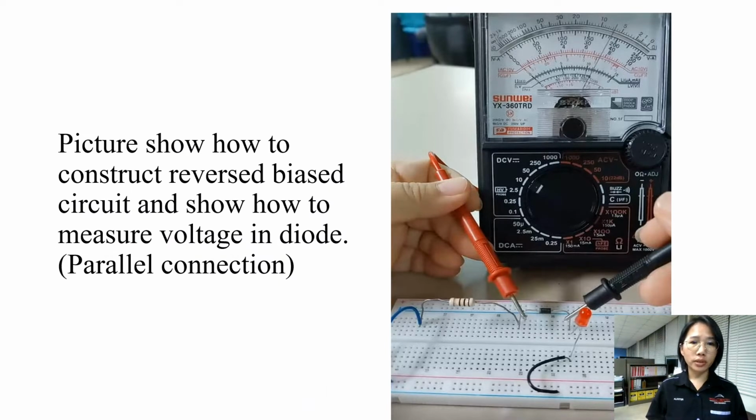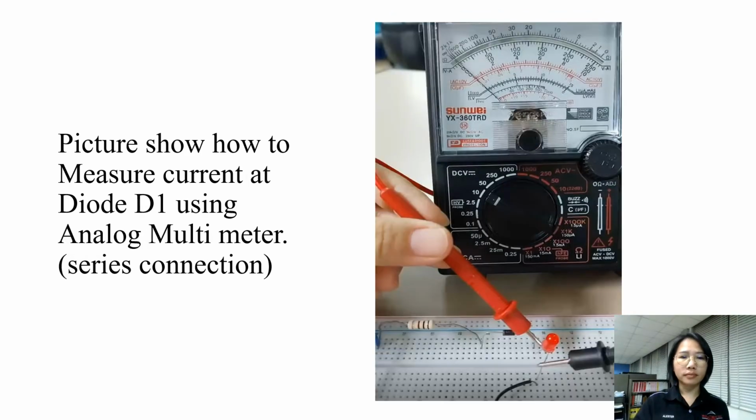This picture shows how to construct reverse bias circuit and how to measure voltage in diode. As you can see, the analog multimeter is connected parallel with the diode. The picture shows how to measure current at diode D1 using analog multimeter, and the analog multimeter connected in series to D1.